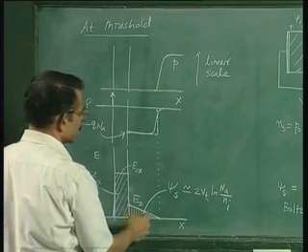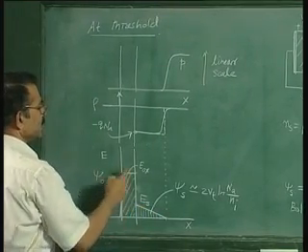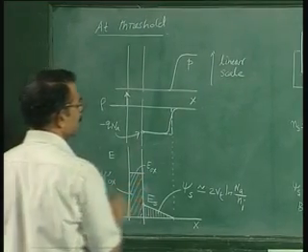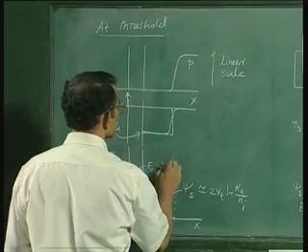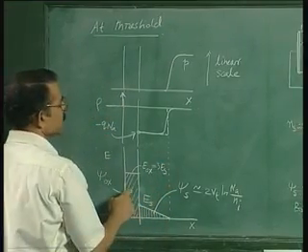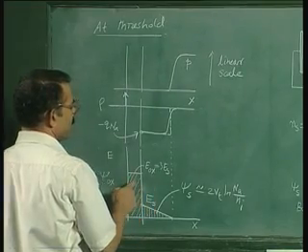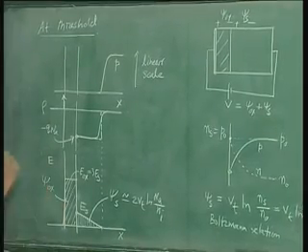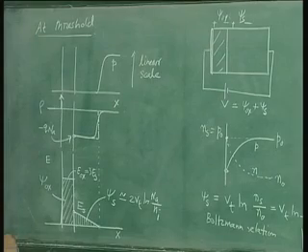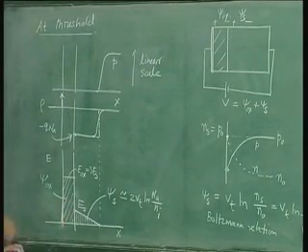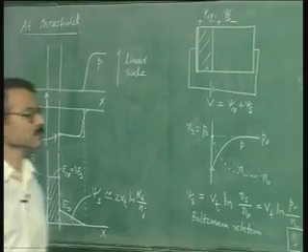Now once we know this, we know this area also, because we know this Eox is 3 times Es, because of the dielectric constants of silicon being 12 and oxide being 4. Therefore now we can write an equation for threshold as follows.